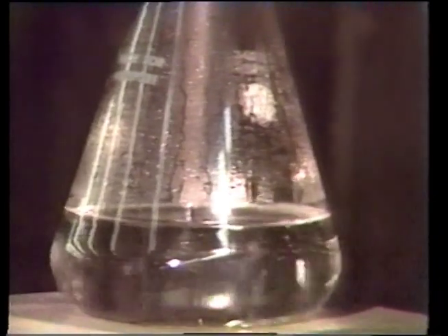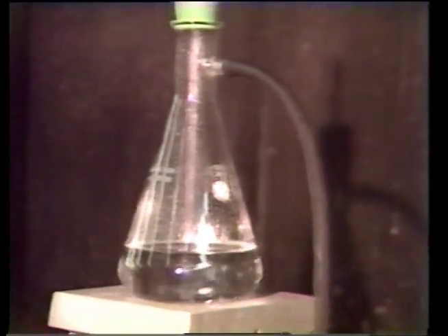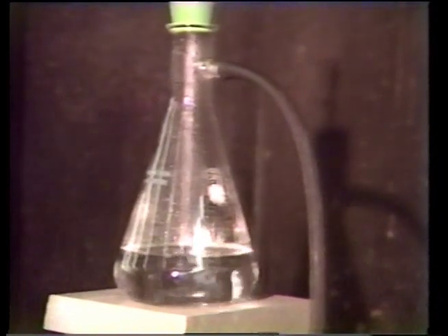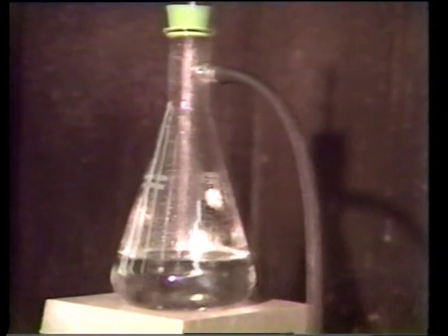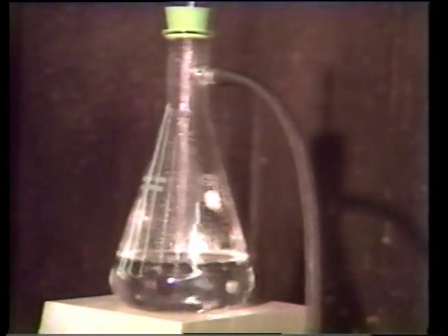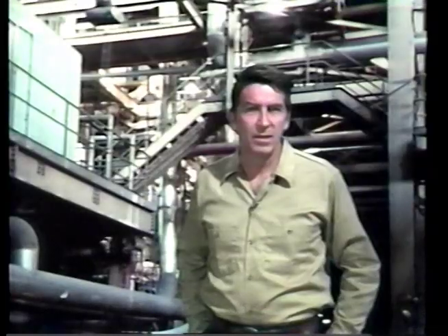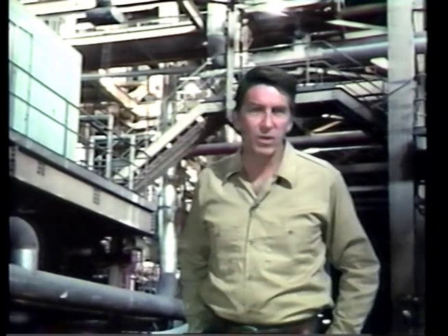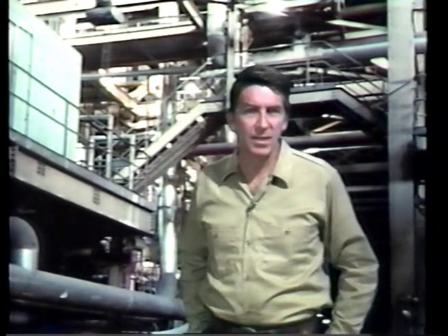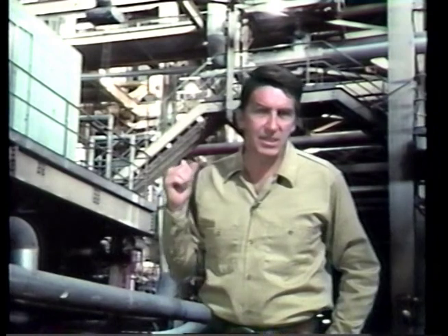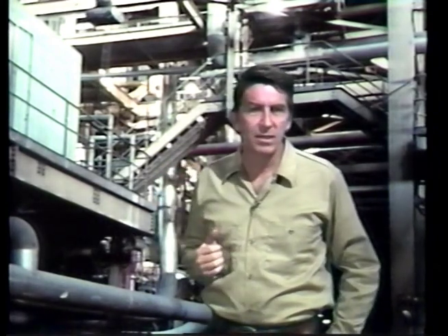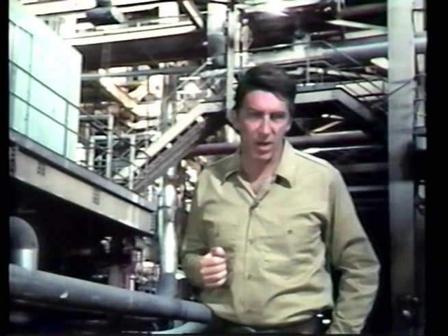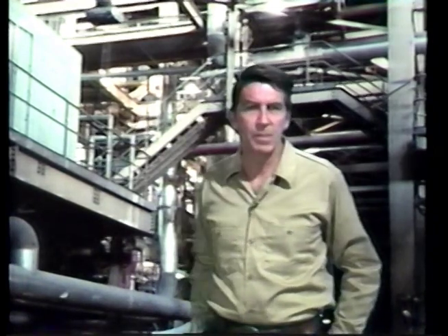If you've ever boiled water, you've seen this same effect. The ambient temperature, in this case the temperature of the area around the flask, is a lot lower than the temperature of the steam inside the flask. So some of the steam condenses on the sides of the flask and drips back into the boiling water. Now, if you're just boiling water, this isn't much of a problem. But if you're sending steam to various types of process equipment throughout your plant, this condensate can be a big problem. All right, now let's see why.